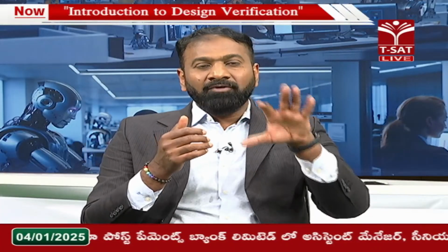In the SystemVerilog test bench environment, I have a generator which will generate the input stimulus. I have a driver which will apply the stimulus to the device under test or the RTL design, and then I will be monitoring the inputs and outputs and ensuring that coverage of my requirements is met or not. So, that is my complete SystemVerilog test bench environment. And now I will create different tests for different kinds of scenarios and requirements, and these will be added into a program block. We will see more about how the actual data flow happens, but at a high level this is the SystemVerilog test bench environment which you can refer to.